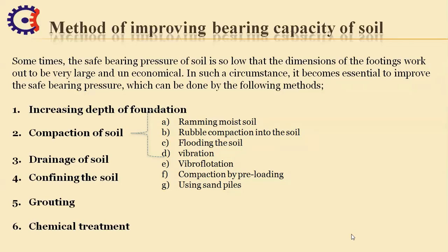First is increasing the depth of the foundation. At deeper depth, the overburden pressure on soil is higher, hence the soil is more compacted at deeper depth. As a result, it shows higher bearing capacity. This is applicable only for cohesionless soil such as sandy or gravelly soil. This method of improving bearing capacity of soil is not applicable if the subsoil material grows wetter as depth increases. This method has limited use because with the increase in depth, the weight and the cost of foundation will also increase.